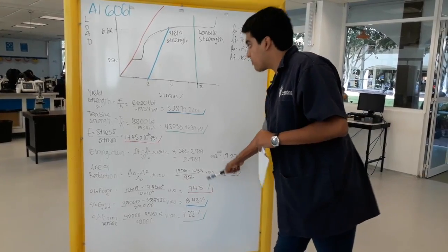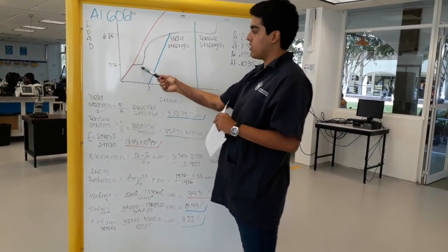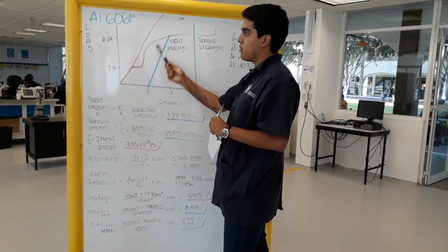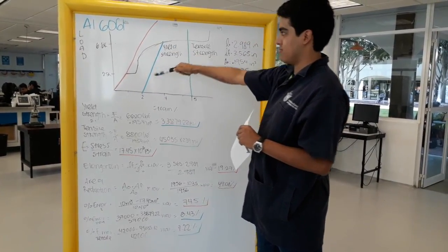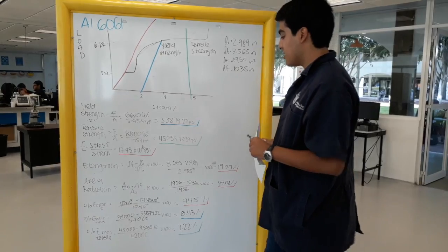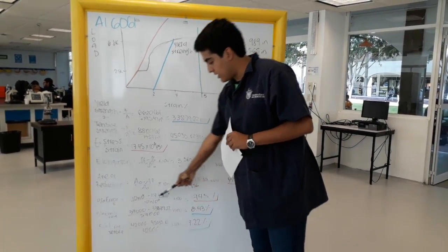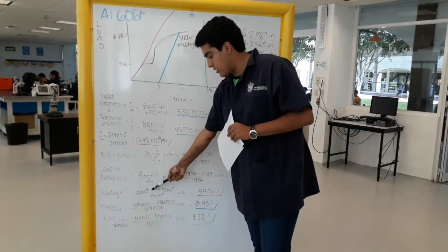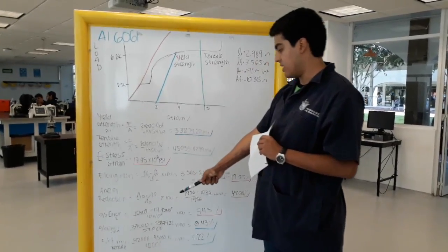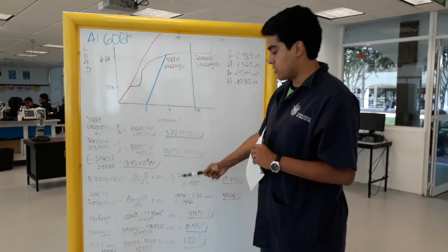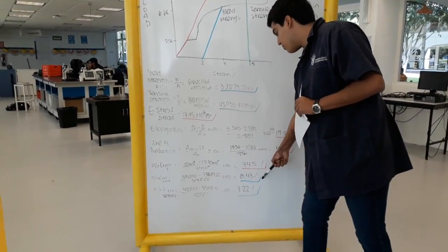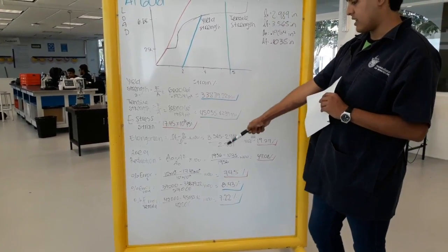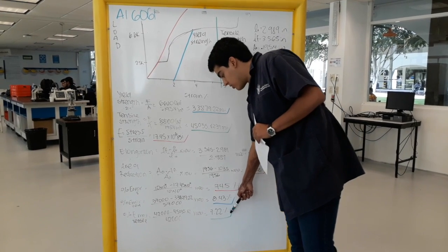This was too big because when we use the machine, we move the material, so the graph was a little bit strange. With the values from the tables, the percentage of error of the yield strength was 8.47% and the tensile percentage of error was 7.22%.